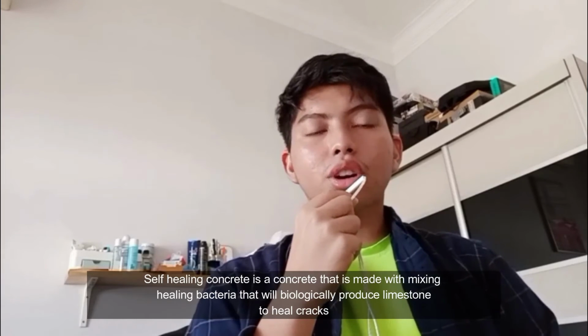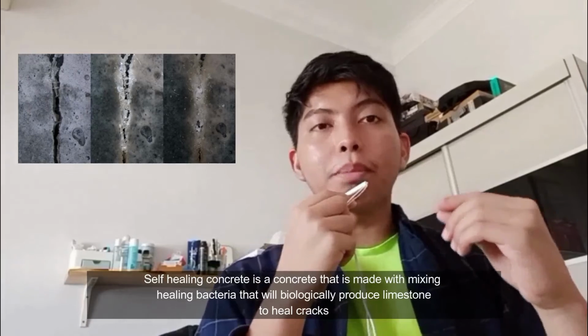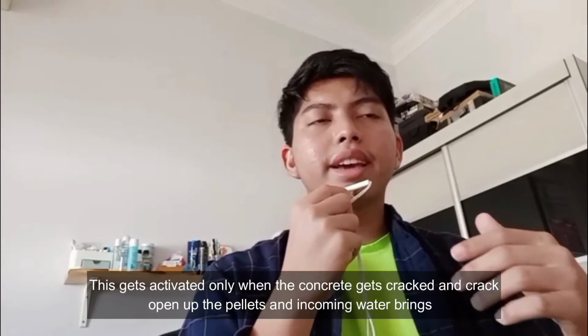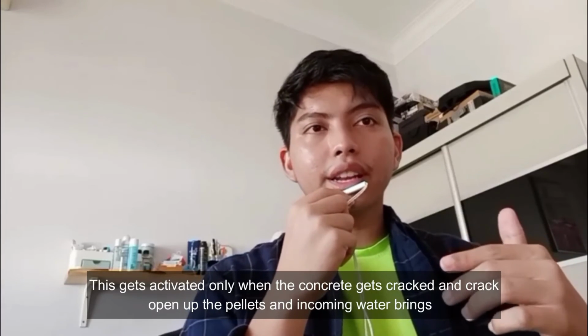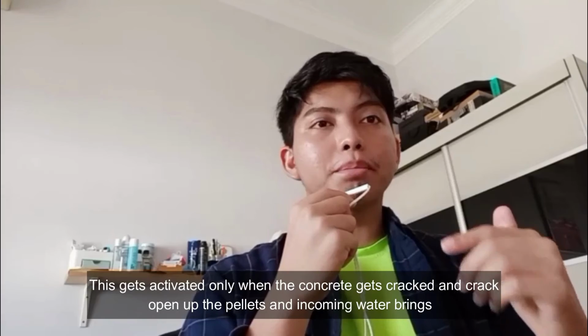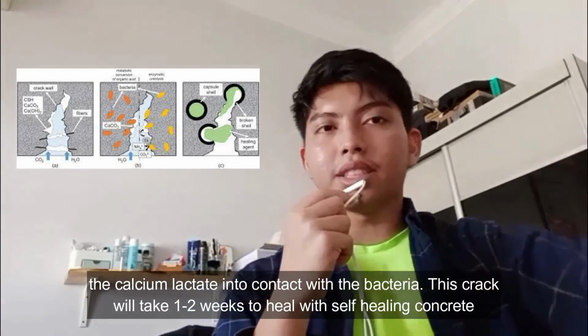Self-healing concrete is concrete made by mixing in healing bacteria that will biologically produce limestone to heal cracks. This gets activated only when the concrete gets cracked, and the crack opens up the pellets, and incoming water brings the calcium lactate into contact with the bacteria.